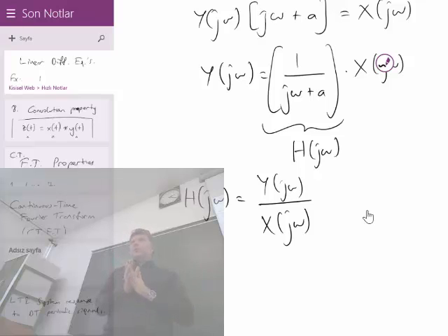It's not true. Please do not write it that way, because I am sure in some of the examinations I will encounter this. Some of the students who are not here today, probably, will write in their examinations h(t) is equal to y(t) over x(t). They will write it, which is very incorrect. But in the frequency domain it is correct. In the time domain, y(t) is h(t) convolution x(t). That's a very different operator. It's not multiplication, it's convolution. But when you take the Fourier transform of every side, this is what you can have.